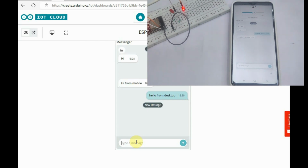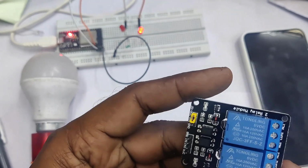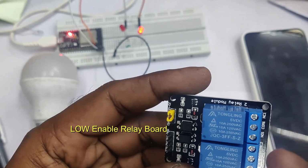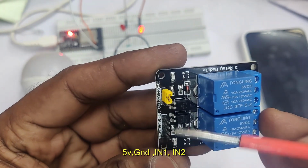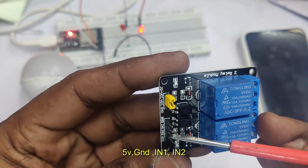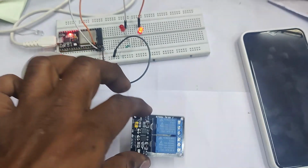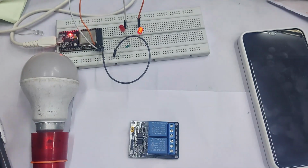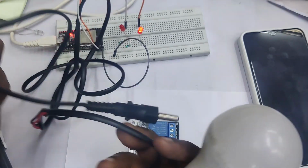Next we'll configure the relay board so that we can connect the actual devices for home automation. This is actually a low enabled relay board. When a low is applied to the input, the relay will be on. The pins are 5 volt, ground, IN1 to control first relay, IN2 to control the second relay, and the output can be taken at the relay contact screw pins, blue pins.